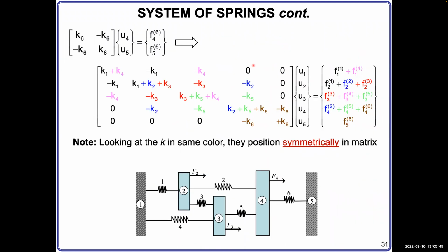And note, when you do this, you actually add the spring constant into the stiffness matrix. You will leave the displacement intact, because displacement is shared by all these springs. When they move, because they are all connected with one rigid body, that rigid body has only one displacement. So at that node, all the displacements are the same.